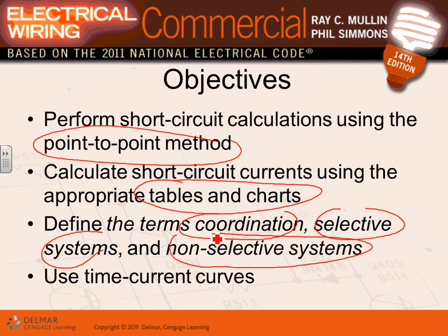Imagine if Brian is changing the ballast on this fixture, and all of a sudden shorts it to the ground, and the 3,000 amp main at Dunwoody trips on a ground fault. That's bad news. Imagine that happening in a hospital. Imagine that happening in a stadium while you're watching your favorite show or favorite play. That's very bad news. So that's why coordination is a big deal.